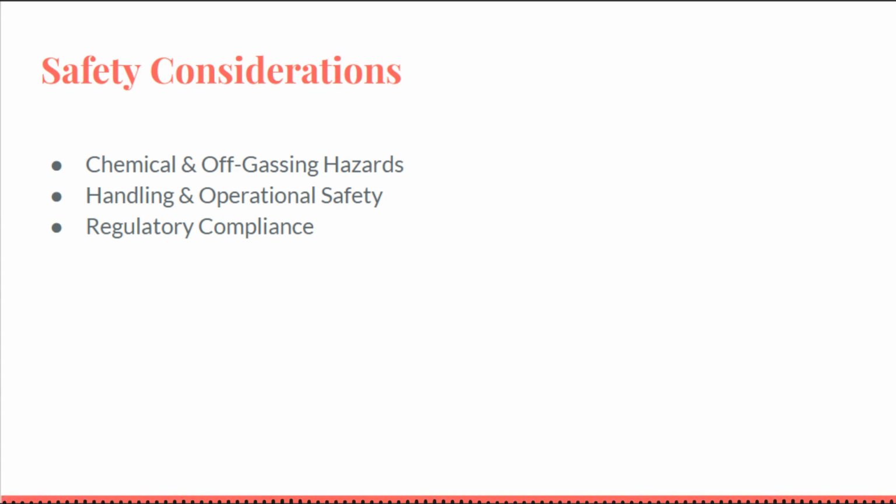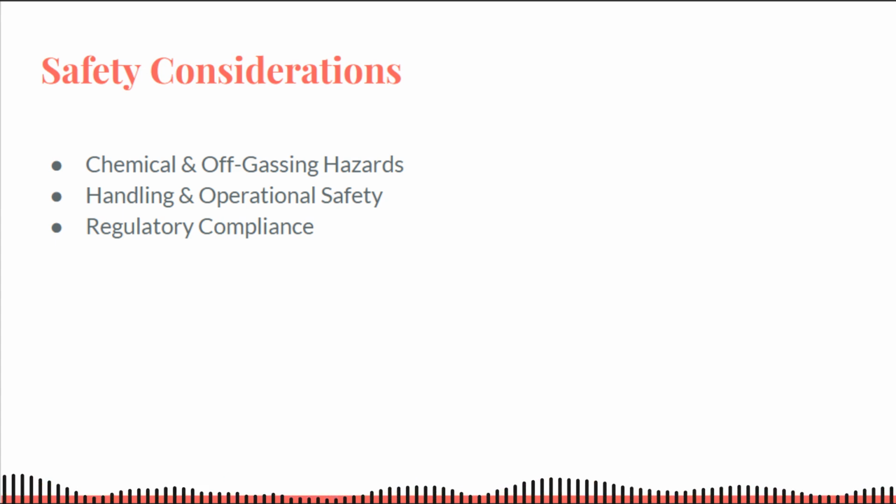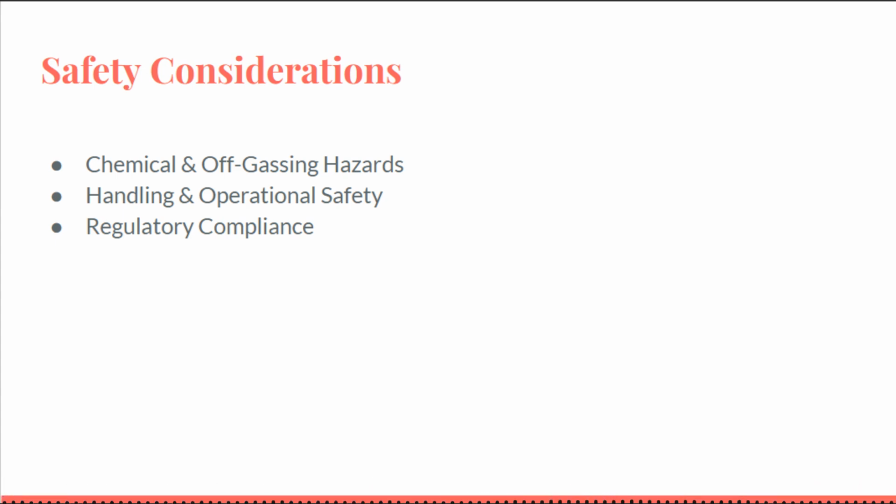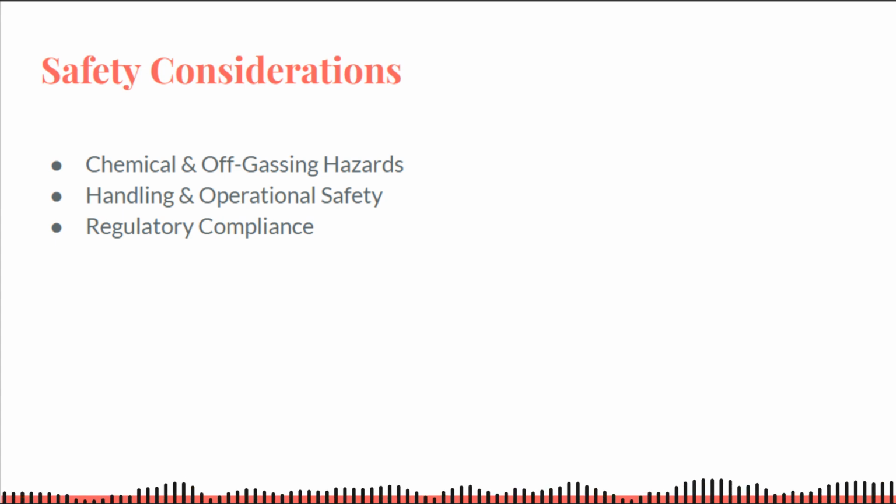Regulatory compliance. According to industry standards, ANSI APSP 5 and the Model Aquatic Health Code, ozone or AOP must be used only as secondary supplemental systems alongside a primary residual sanitizer. This means you must still maintain a minimum chlorine or bromine level in the pool water to meet health codes. Ozone and AOP are not standalone sanitizers. They are, however, recognized for improving water quality. The CDC and PHTA recommend supplemental systems, especially for high-risk or heavily used pools, to boost disinfection and reduce byproducts.